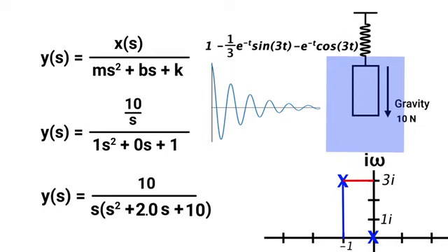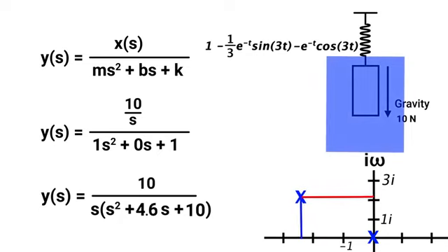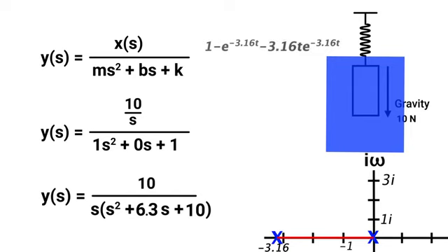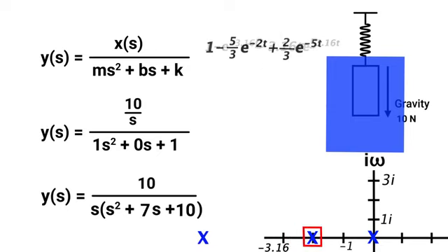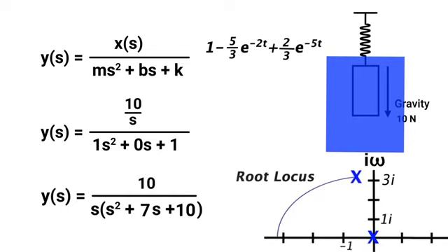If we make the damping much stronger, we get to a point of critical damping, where finally oscillations go away and it's only exponential decay. Then moving from there, the exponential decay just slows down from this term not decaying as fast. Plotting the path those poles just took is the idea behind a root locus plot, by the way, for those in the controls class. But this is where the design part comes in, because by analyzing the locations of the poles, we can determine how a system will respond to different inputs.